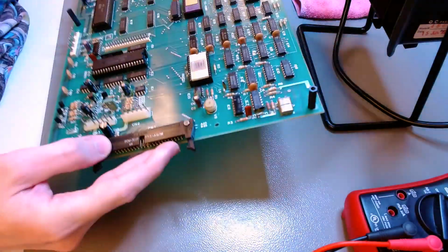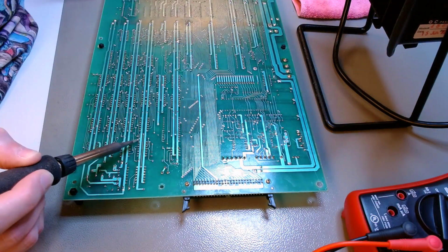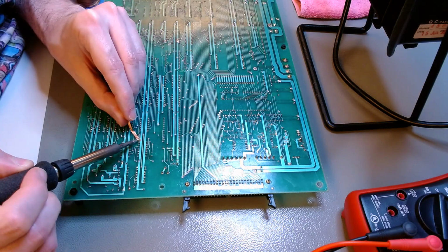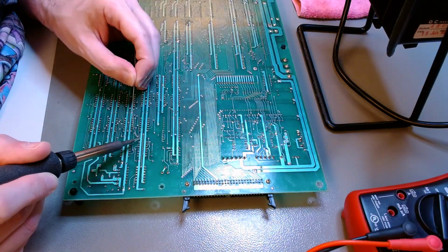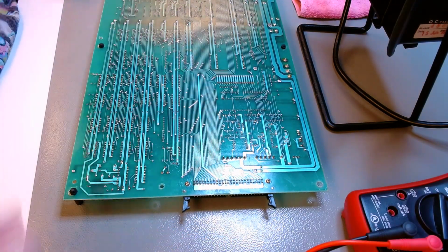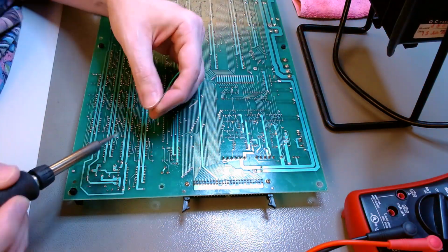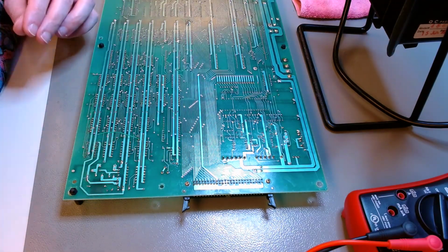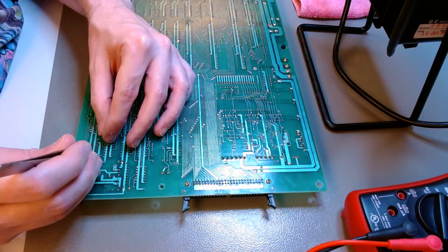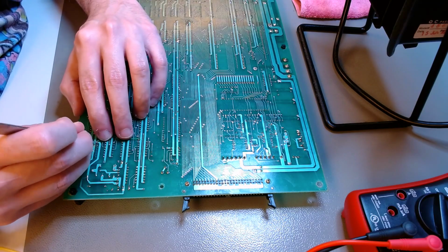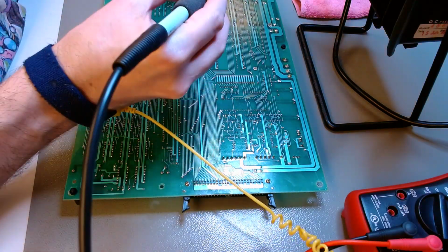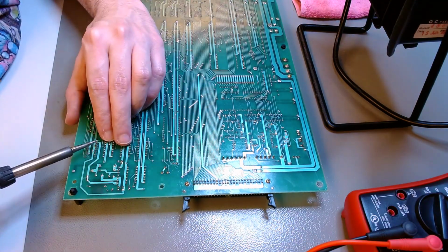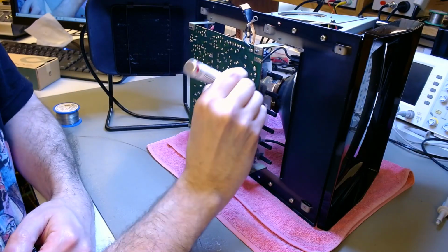After I tried it once, I didn't quite like the result. So I removed everything, cleaned the solder again, and I will do it again until I am satisfied that it's up to standard. There goes the bodge again. Fairly clean, with a little hook on the wire for mechanical sturdiness. Solder it in place, and this should solve the problem.